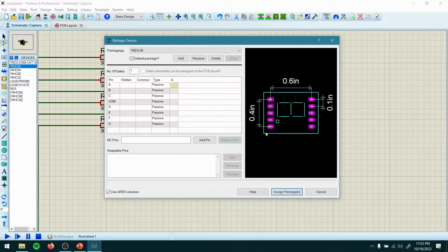Okay, in this column all the PCB package pins should go, and as this is pin A, it should be linked with pin A from this diagram, right? So let's look for pin A. This is pin A, right? So let's click here. If I click here, you see A1 is written here. That means pin A and here pin A1 is matched. So the schematic and PCB package pin got linked up. In this way, all the pins should be linked. For B, it should be B1, right? Let's press B1. Where's B1? Yeah, B1. Then C, C1, press C, then common pin.